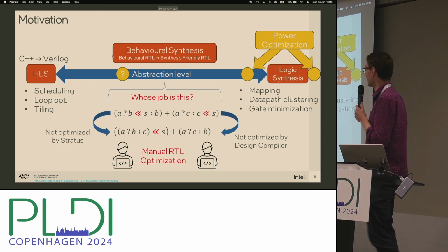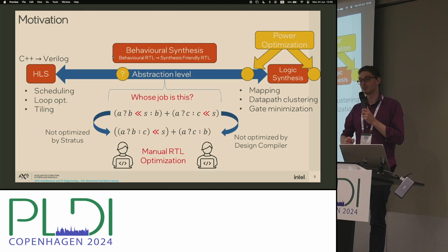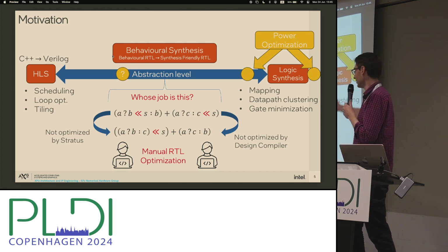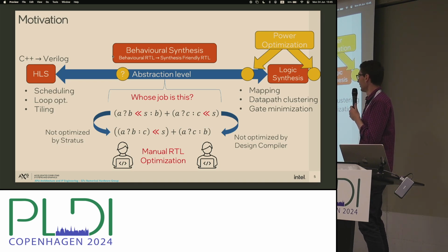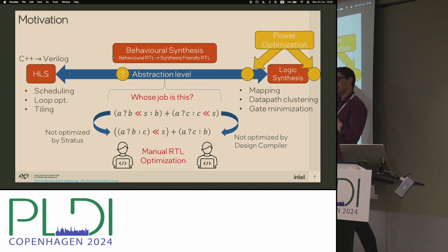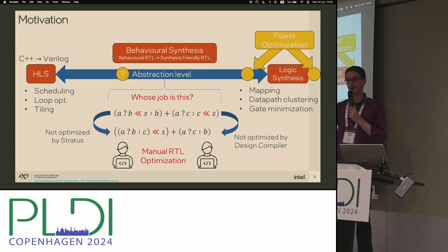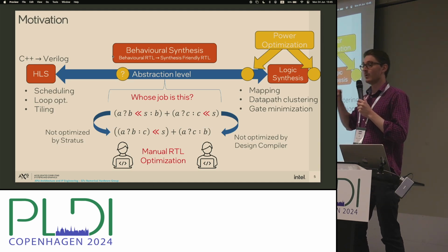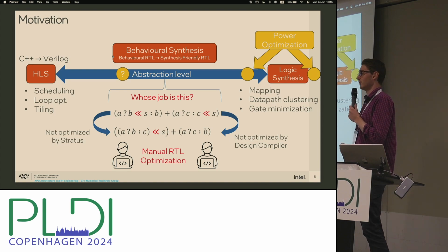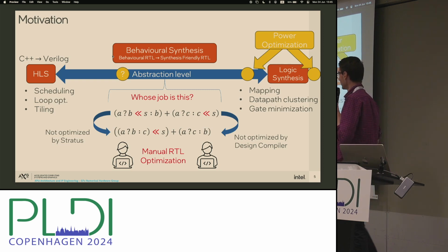And that's where this kind of behavioral synthesis idea comes in, which is basically taking kind of word-level hardware designs and trying to do these sort of transformations. That's where really all my work has been focused. And now really we're looking at power optimization, which again really sticks on this right-hand side of this kind of abstraction level. So really we tend to look at fixed data flow graphs, and we're shoving in operators to try and reduce the power consumption. We're just kind of making tweaks after we've basically figured out what design we want to do.